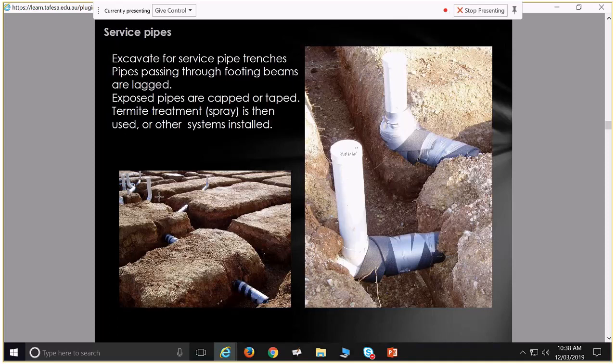Okay. But your lagging detail is important, and I would take issue with seeing something like that on site, because what we've got happening here, yes, that pipe is lagged fairly well to that side there, but here we've got concrete right around that section. So that lagging isn't really doing much if the edge of our pipe is so exposed and is going to get all covered by concrete there. It's not going to allow much movement. So tiny little details like that can be very important.